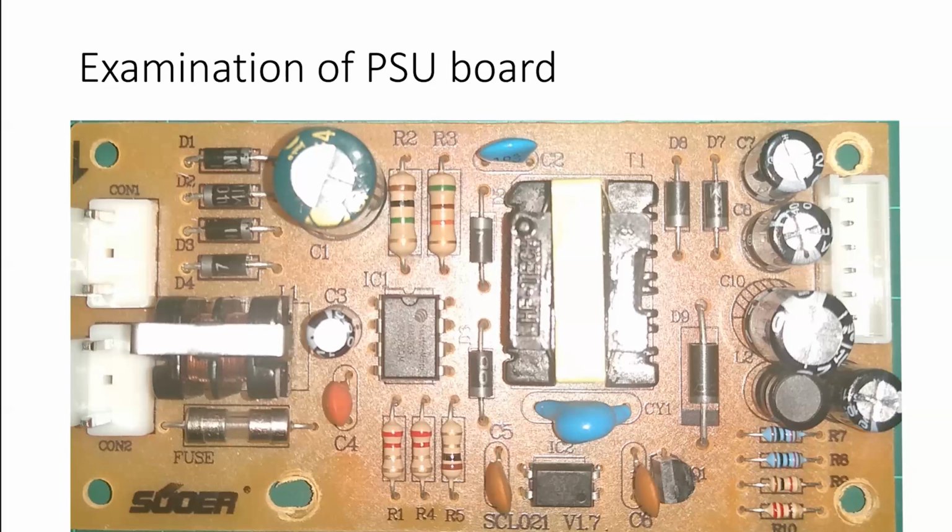And then at the bottom there, we've got a voltage divider in Q1. I suspect Q1's probably a transistor or maybe an SCR, and that's supplying feedback back to the opto isolator to send back to the chip.